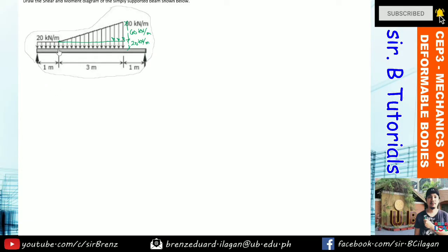Since these are all downward forces, for the reactions, let's just say that this is point A, this is point B, and then dito sa intersection ng mga load, this is point C, and this is point D. So the reaction here, I will name as AY, and ito si BY. Pili ka na lang sa dalawa kung saan mo gusto mag-moment, pero ako, I would prefer na dito na lang mag-moment sa point A para makuha yung value ng BY.